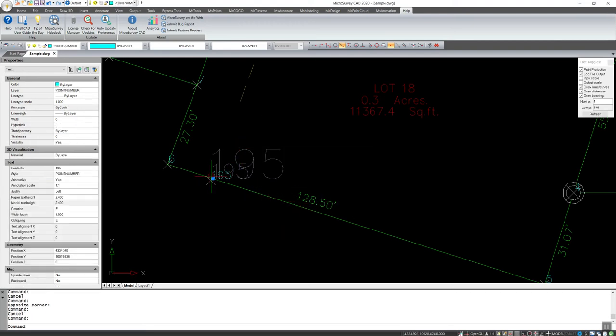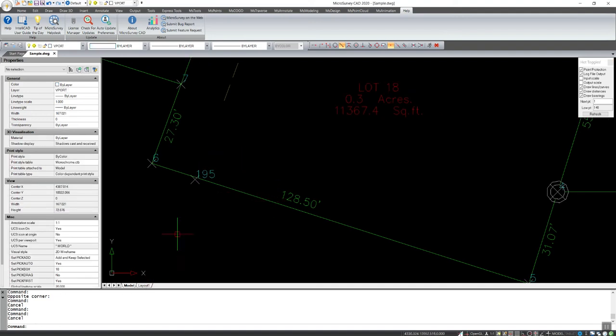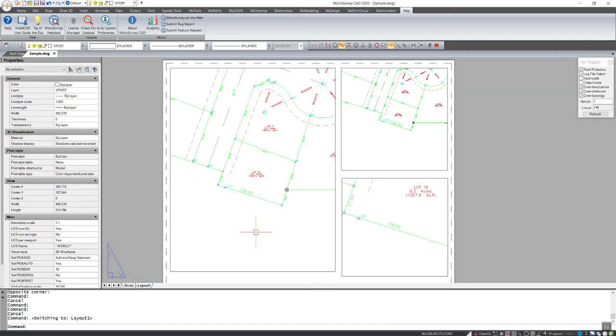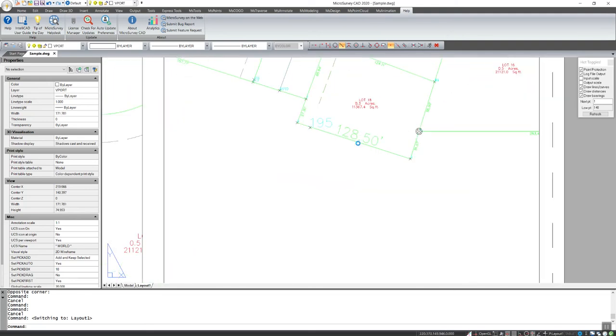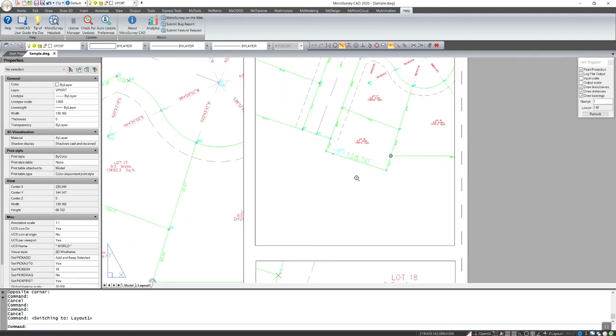Now when I select the text, you can see also the two larger sizes and where they'll be in the drawing. So now that I have my text set to be annotative and I have defined a couple of extra scales in there, I'll switch to my layout, and this is where I have a few viewports. If you'll notice, for example on this one here, the two texts I've made annotative are larger than everything else.